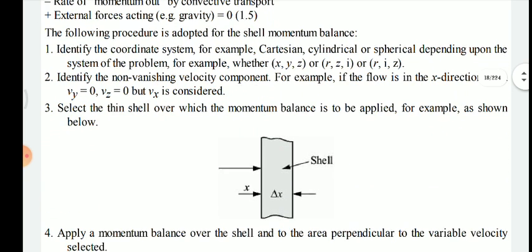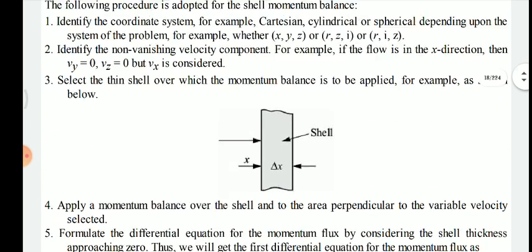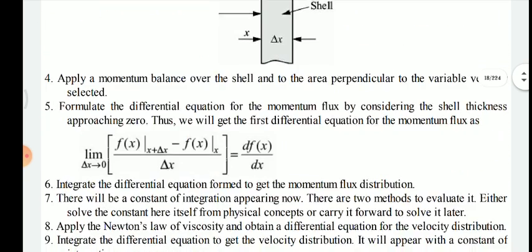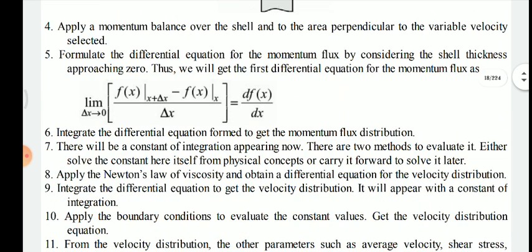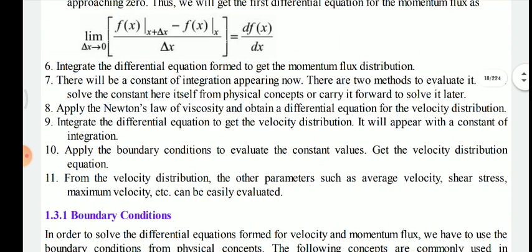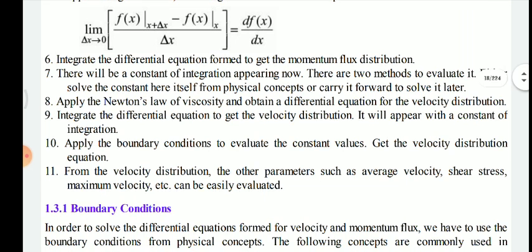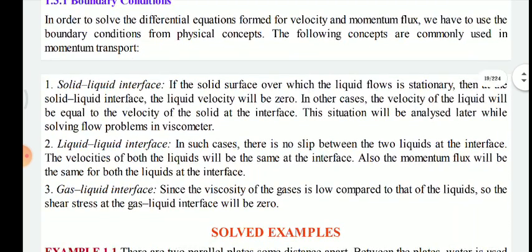Then identify the velocity component, formulate it into the differential form, and integrate it. Apply Newton's law of viscosity, then apply shear stress or find the velocity distribution and other parameters like average velocity and maximum velocity. And here are the boundary conditions for solid-liquid and liquid-gas interfaces.